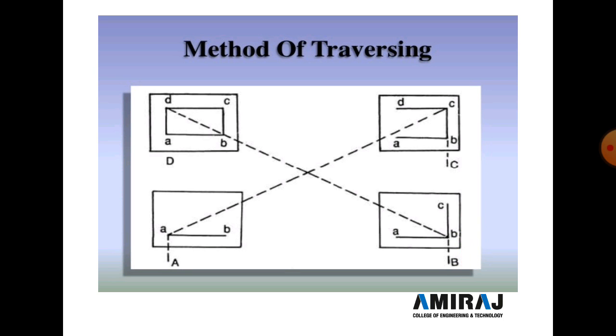The B to C distance is measured by the measuring tape and we take a scale of 1:1. Like the B to C distance here is 20 meters, so with scale 1:1, meaning 1 meter is equal to 1 centimeter, we draw the small bc line 20 centimeters. Similarly, repeat the same thing and transfer the table to the C point and bisect the B point.